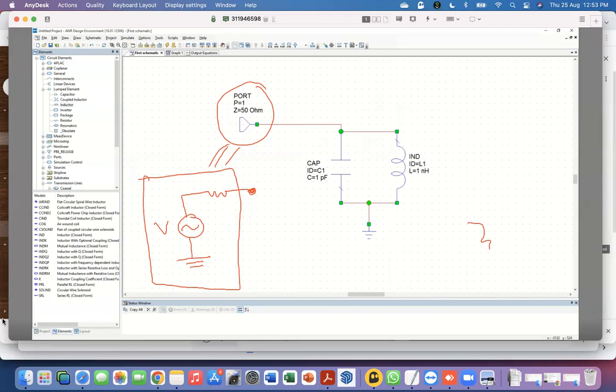I don't know whether you remember this concept, but an ideal voltage source has zero internal impedance, which means that this part of the circuit doesn't have any resistance. So the previous model with only the resistor is still valid. From the point of view of the circuit, it looks like a 50 ohm resistor, so this is 50 ohms connected to ground. And if you have a voltage which is finite, then of course that rides on top of that.